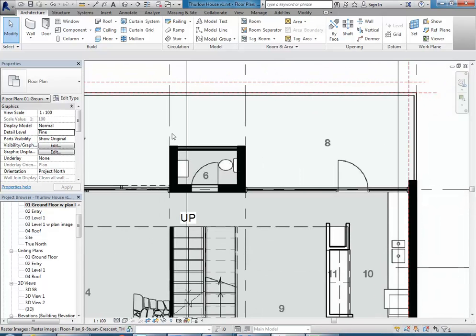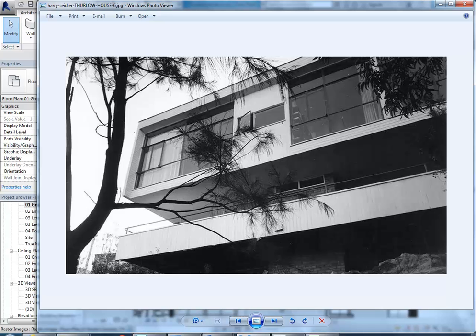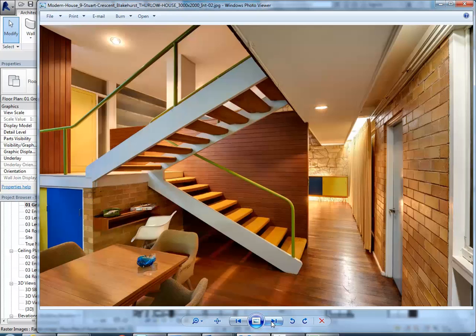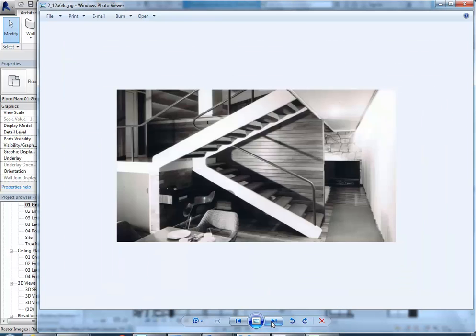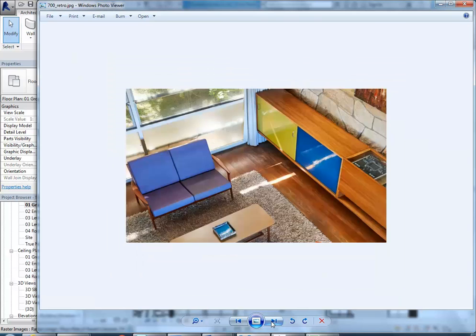I think that would be typical of him actually, because he tied his design into the structure, and I just don't see how you can remove that without totally compromising the structure. So what they're saying, remove the whole bathroom. Yeah, the brick external wall. Oh, right, so keeping the brick external wall, like the wall that's between the windows. I suppose you could, yeah. Would that be structural? Yeah, it would, because it would cantilever from there. But I'd say you could do it, you just have to put in bigger beams.